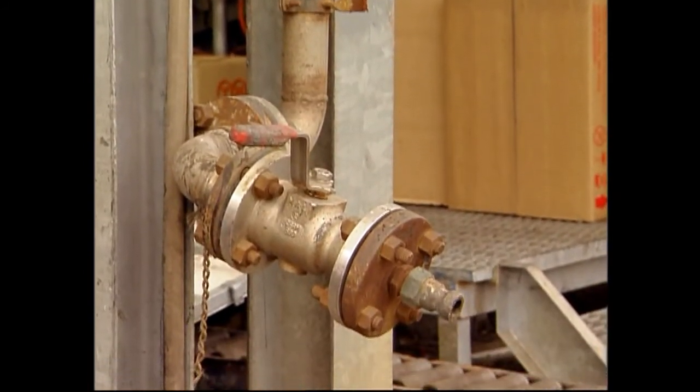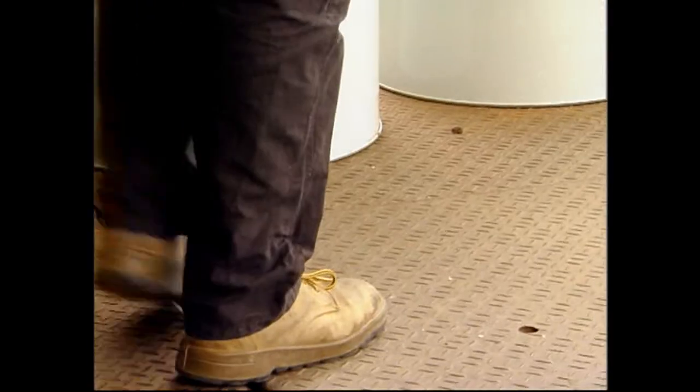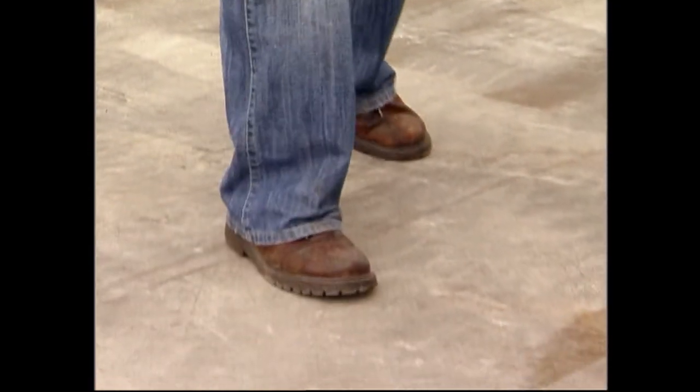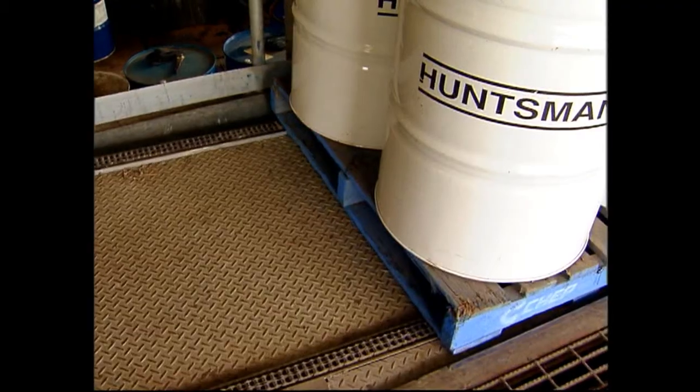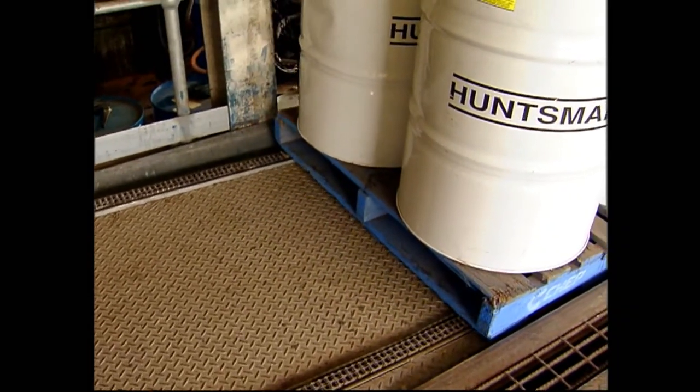In areas where static is a potential hazard, both work surfaces and floor surfaces should be made from conductive materials such as metal, conductive plastic, conductive rubber, untreated wood and unpainted concrete. Surfaces should be kept clean and free of oils, resins, waxes,